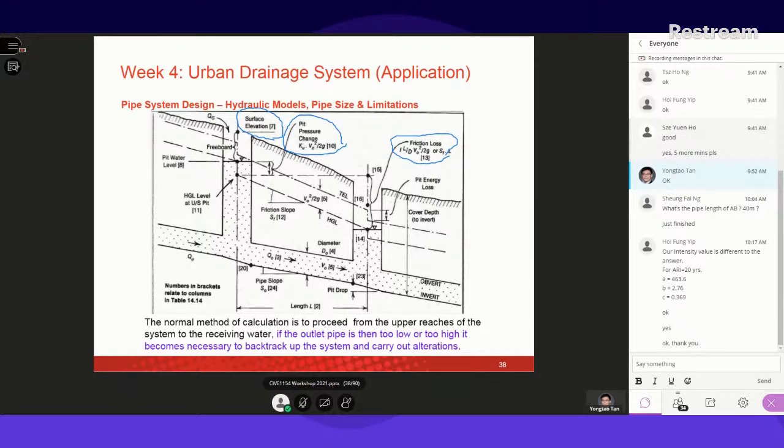For the pit pressure change, the manholes and pits are nearly always larger than the pipes, and there is also the expansion of the pipe flows, the mixing of the pipe and surface inflows, and the effects of downstream water levels, which create complex flow conditions at the pit. This will result in energy loss and increase the water level, sometimes causing overflows.